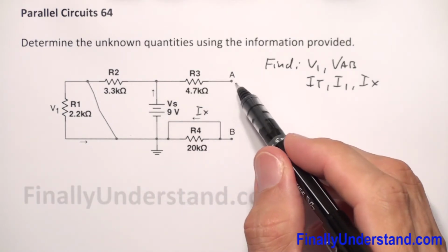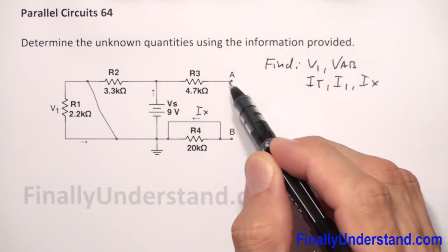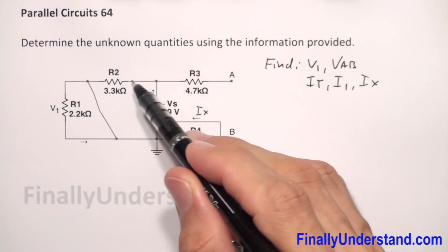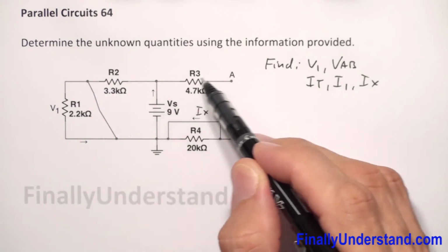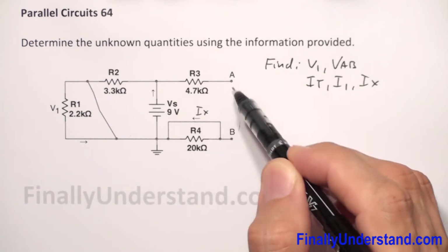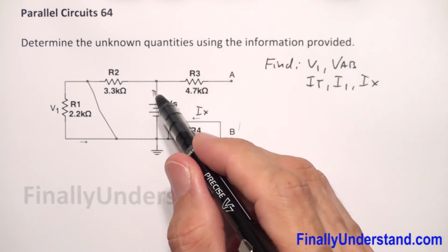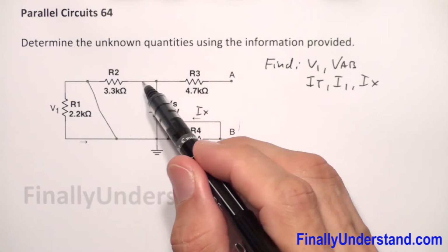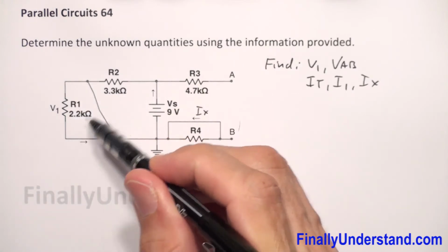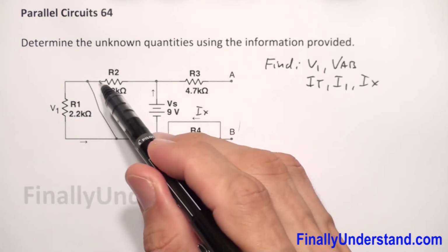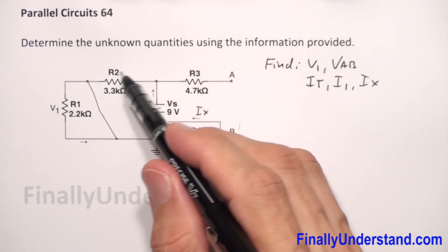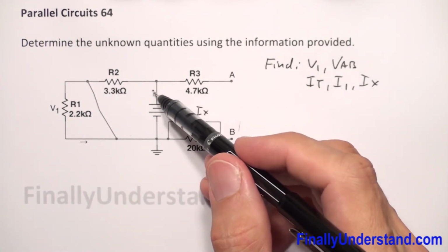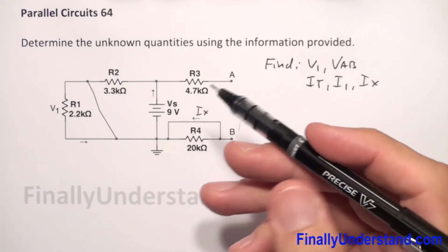Okay, because current sees this gap, like extremely high resistance. So it's much easier for current to go this way to the ground instead of going this way. That's why current is going to ignore this way completely. That's why entire current is going to go to the left. And please notice what happened. Current is seeing over here resistance, and over here is seeing the short, right? Like a shortcut. So current definitely is not going to go through the resistance, because current is a very lazy guy and is always looking for the opportunity to reach the ground in the simplest way.